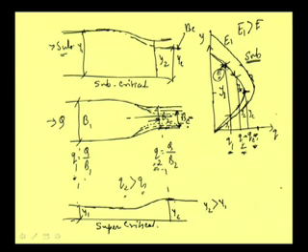And at this higher energy level, what will happen, and to what extent will it rise? It is rising just to push the water through this point, and it can push the water when the depth at this narrow portion is again critical. That is, the maximum discharge possible here is at the critical section.